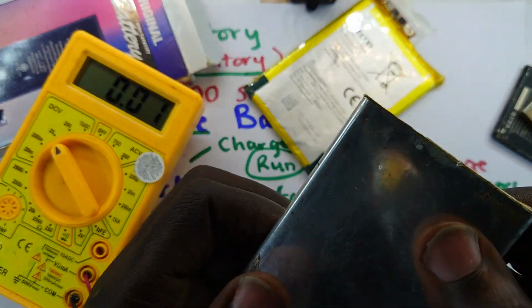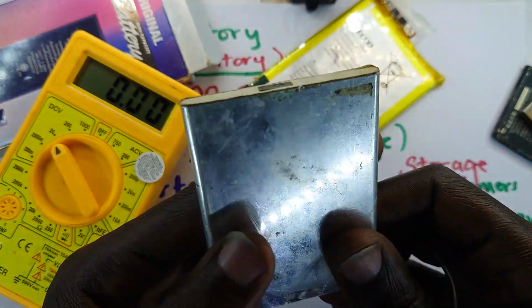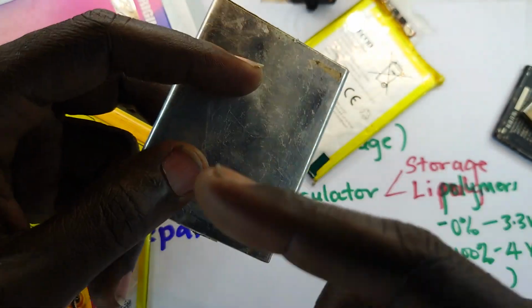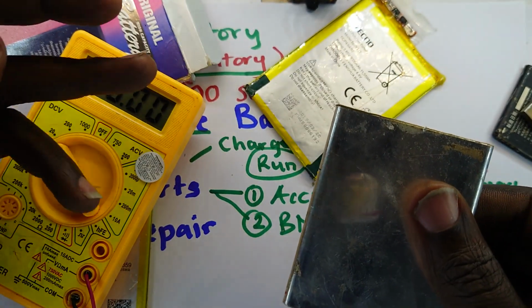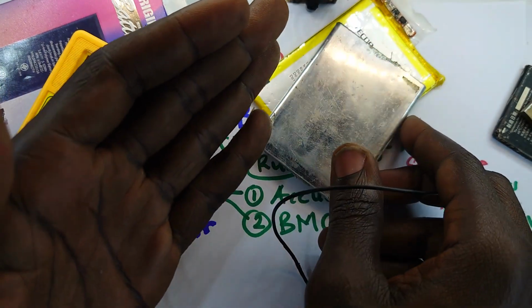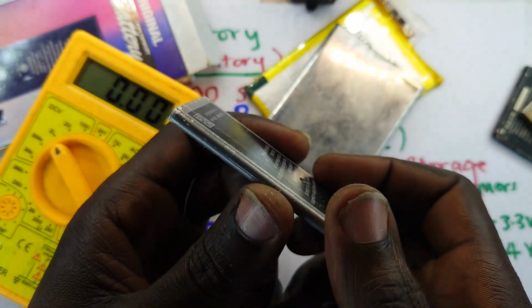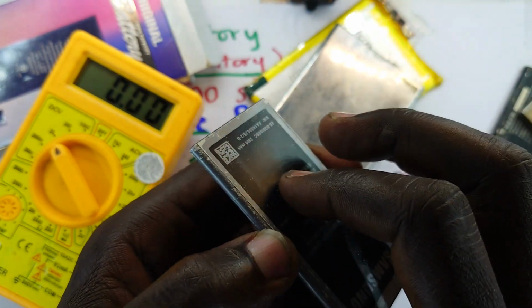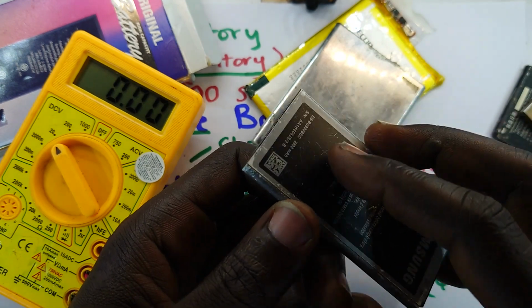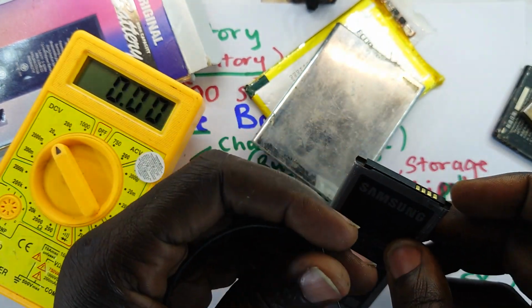This means this battery is likely good, because it has been stashed away for long but still holds its voltage. I'll also show you another thing: at times, in as much as it still has charge, it may not hold charge for long. Those are scenarios where, like you would see with this, it's a little swollen and bulged out. This one's capacity tends to be reduced, because the bulging is an effect of gas formed when the chemistry starts deteriorating.